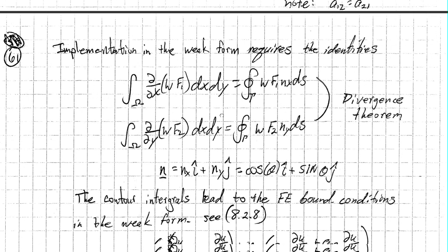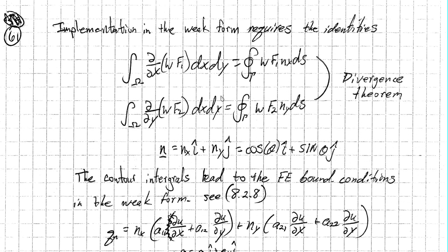Alright, one very important thing. Remember, from 1D problems, we set this up and do an integration by parts, and that gives us the weak form. In 2D it's a little bit more complicated. You can't just extend it exactly the same way to do integration by parts. Instead, we apply what's called the divergence theorem, and I'm not going to go through the proof. This is just something you'll have to remember.